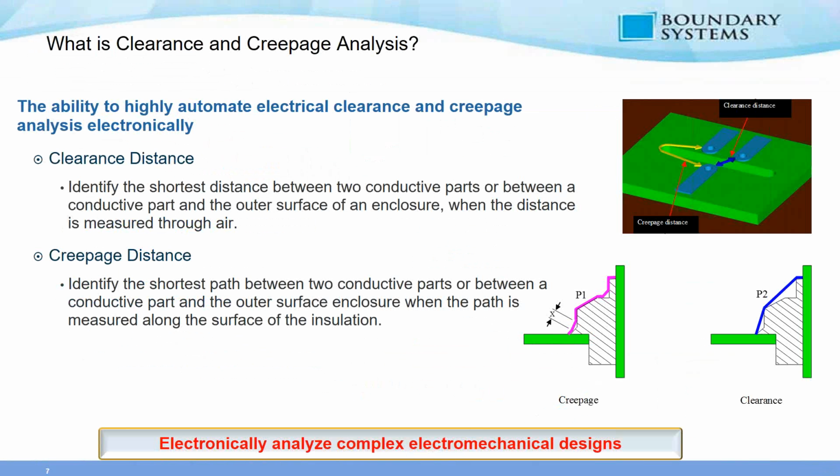Okay, so let's go ahead and jump into what is the Spark Analysis. So the Creepage and Clearance analysis. Okay, so that's essentially what the Spark Analysis tool does. This allows design engineers to electronically analyze their designs to identify if electrical components are violating insulation rules.